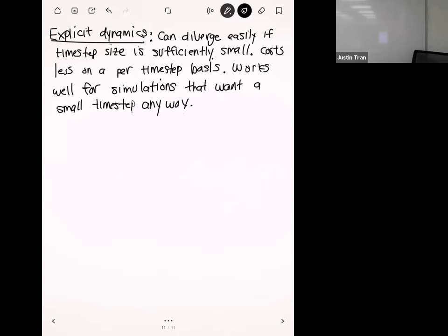You can see, it's just a warning. It doesn't say it's going to fail or stop you. It's just going to say that maybe you might want to calculate this. And if you get that, that's actually exactly what I would teach you. Look at my deformation report, the deformation field. That's fine. I'm getting my max deformation here.